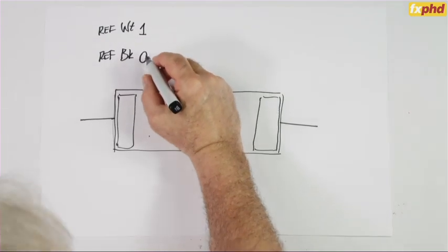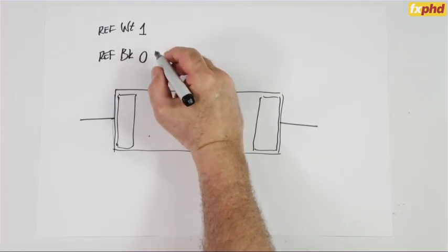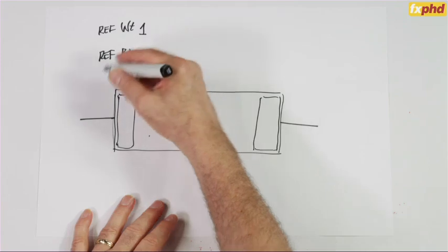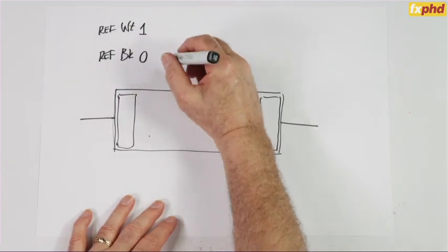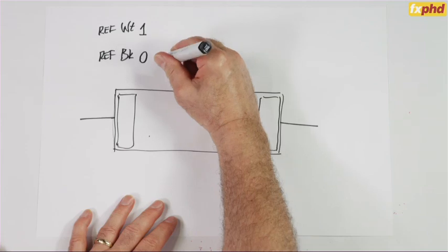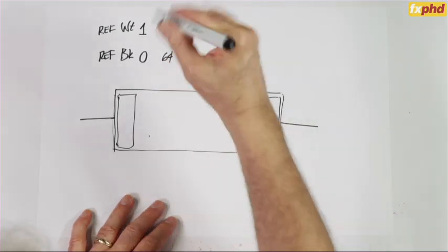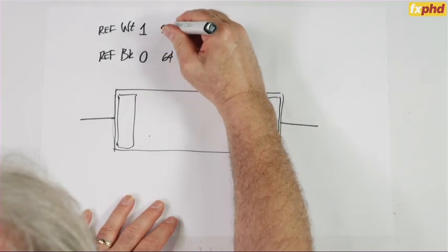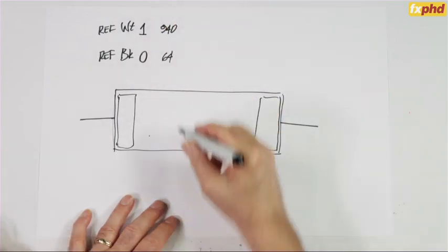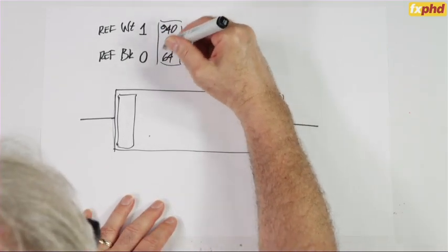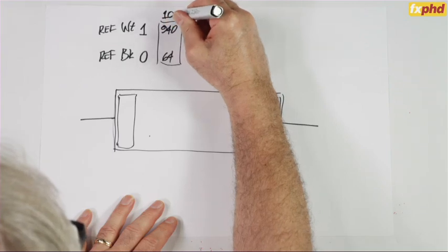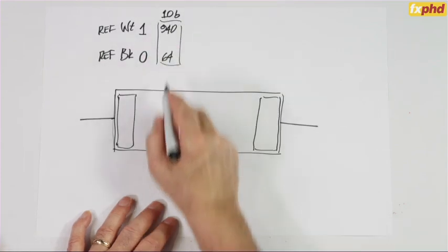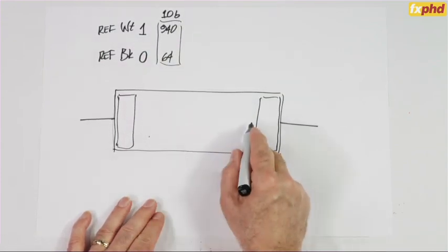And as you've already heard, there's lots of different alternative coding systems, so you'll find lots of people telling you, no, that Poynton, he's a crazy guy. Well, everybody in HD knows that reference black is 64, and I don't know why Poynton keeps talking about 1.0, because really reference white is at code 940. Well, that sort of argument really is limited to 10 bits. And that really is an interface standard. That's not necessarily what's going on in the guts of the grading system at all.